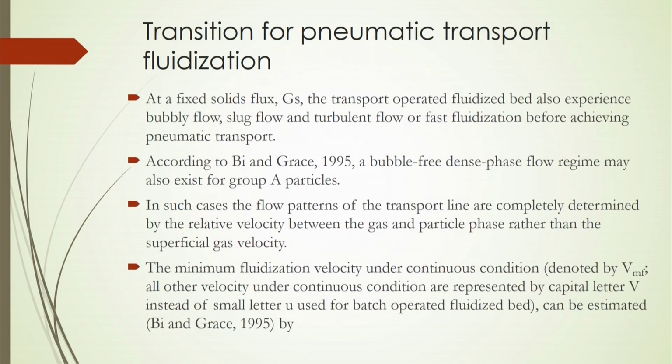And a transition for pneumatic transport fluidization, of course, at a fixed solid flux, the transport operated fluidized bed experiences bubbly, slug flow, turbulent flow or fast fluidization before achieving pneumatic transport. Now, according to Bi and Grace 1995, a bubble free dense phase flow regime may also exist for group A particles. In such cases the flow patterns of the transport line are completely determined by the relative velocity between the gas and the particle phase rather than the superficial gas velocity.